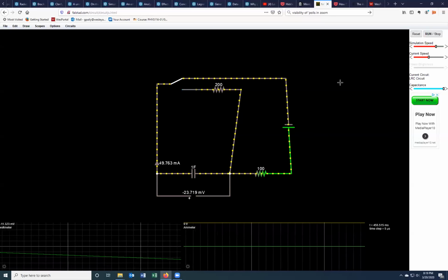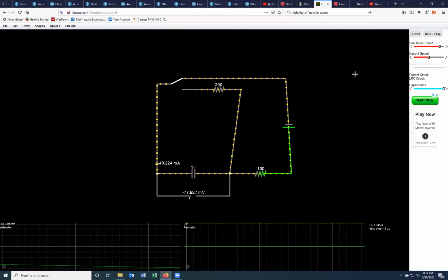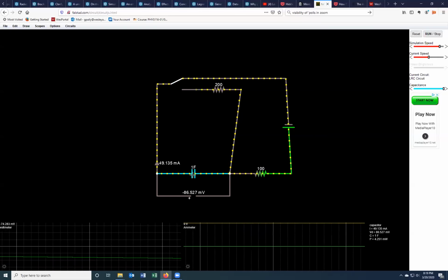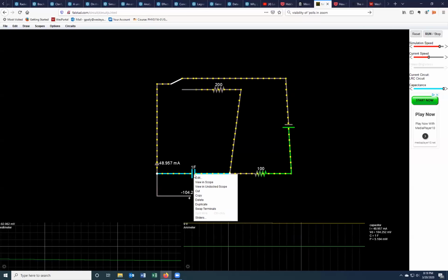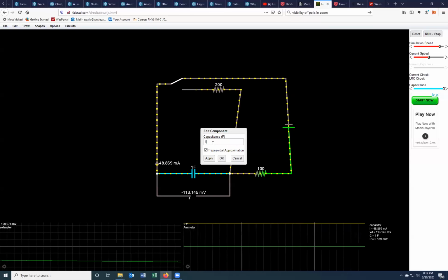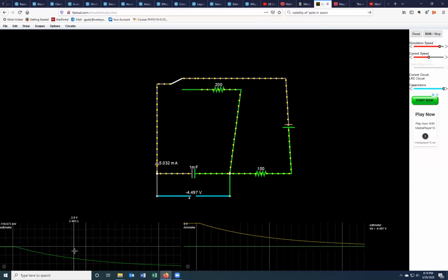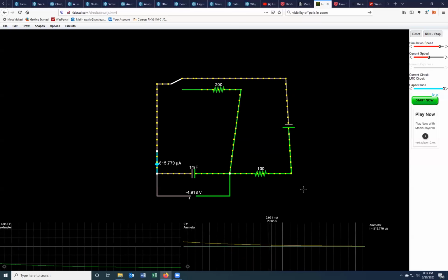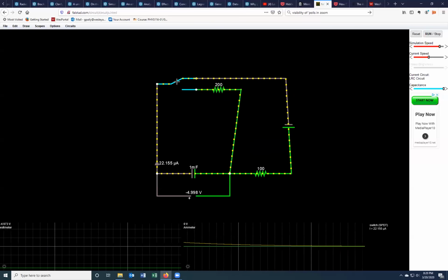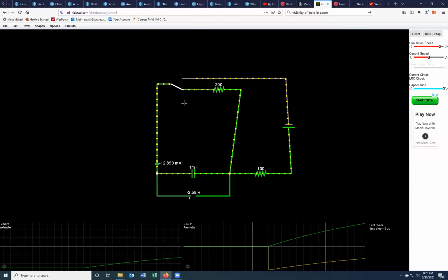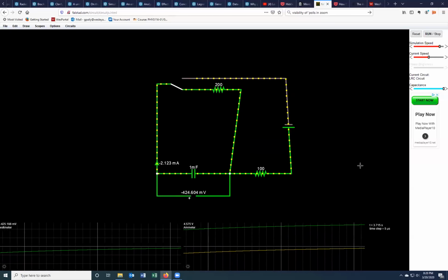Well, before we do that, let's increase the simulation speed a little bit. It's going to take quite a while this way for the charge to build up on the capacitor because it's such a large capacitance. So let's decrease that. Let's make that 1 millifarad. There we go. We see the familiar curves. And now I flip the switch. And we see that the capacitor is starting to discharge. And again, we see familiar exponential type curves.